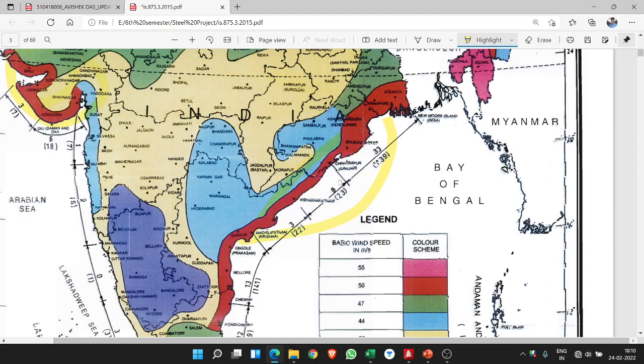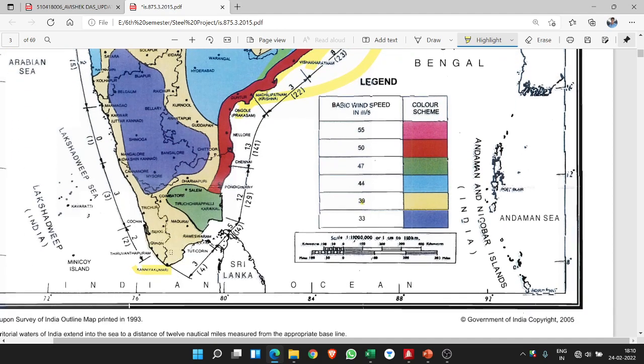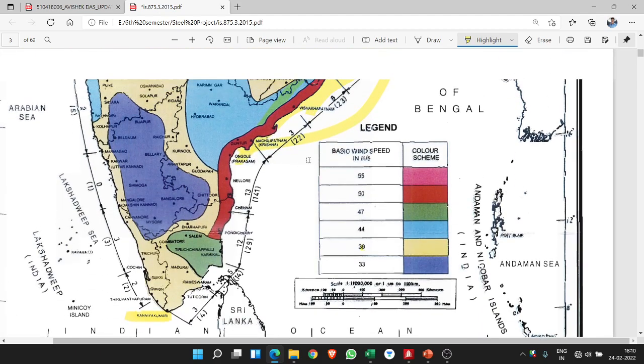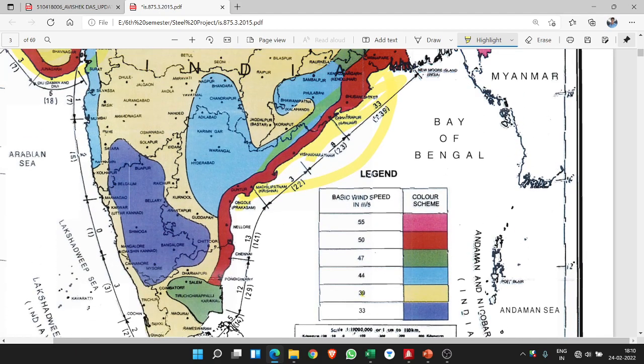So if your location is Vizag or Howrah, Howrah is near Kolkata, so all this comes under the east coast. Mine is Kanyakumari. It is the southmost point, so I'll not consider it as an east coast point, and it's not in Gujarat. So for me, I'll not consider any cyclonic factor. But the one who is in the Gujarat area or cyclonic area, which is within 60 km, Vizag is definitely on the coast. Howrah is also, I don't know the distance from the coast, you have to check that. If you're given Vizag or Bhubaneswar, Bhubaneswar should not be, but Vizag is definitely less than 60 km.